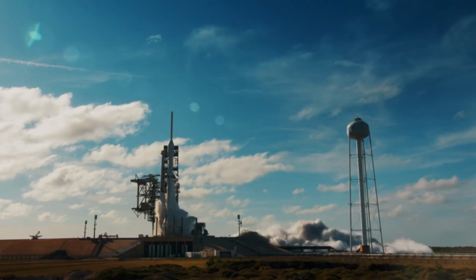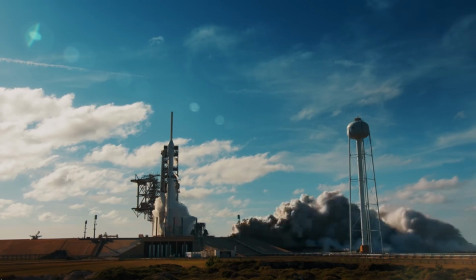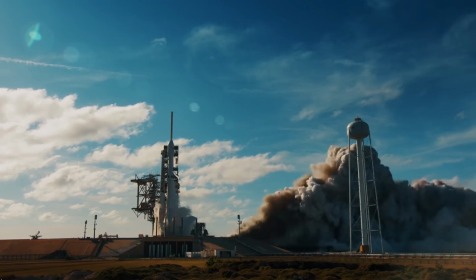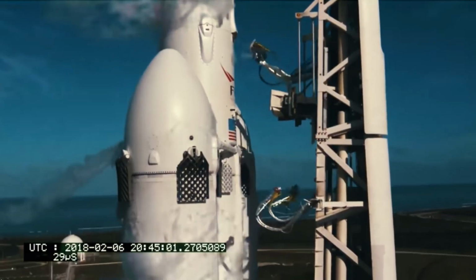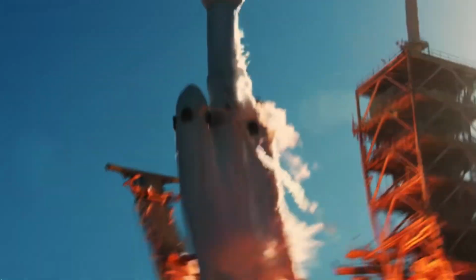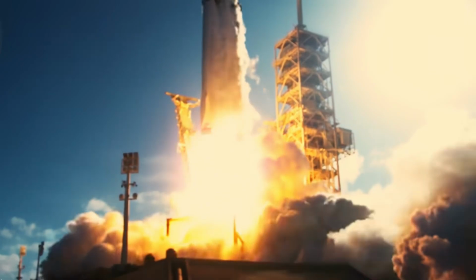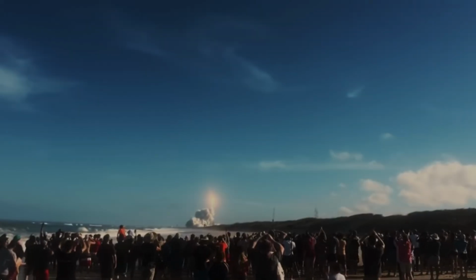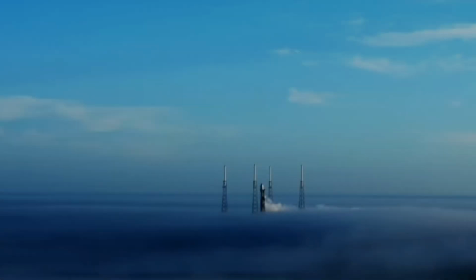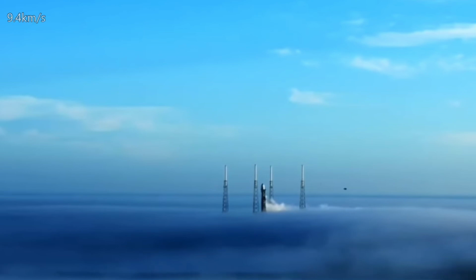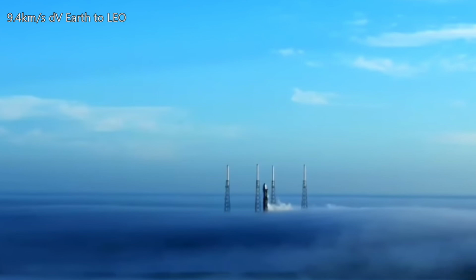Thank you. Today, let's look at designing our own rocket for a lunar mission and comparing our fuel choices. Where would we start? First, what is the mass you want to get into space, and where in space is it going? Let's look at the last question first. In general, remember the number 9.4 kilometers per second. This is a good delta V estimate to launch from the Earth.